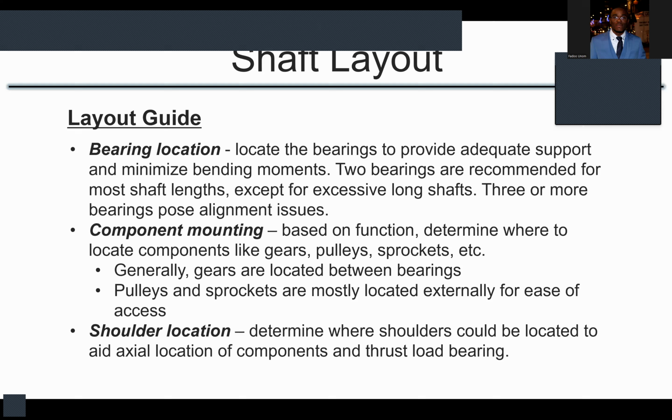Okay, so mounting is dependent on function. Gears are usually located in between the bearings. So your bearings are located at the two extreme ends of your shaft, and then your gears are located within. All right. For things like pulleys and sprockets, the pulleys are located external, outside the bearings.